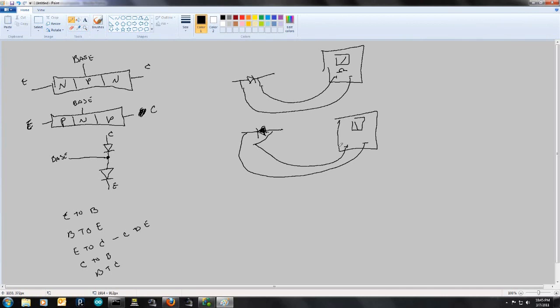So you should measure a very high resistance in one direction and a low to moderate resistance in the other direction, depending on how you're measuring. But basically, how I do it, and I won't go through all this: first of all, PNPs and NPNs are relatively inexpensive. It's a lot harder to measure these components when they're actually in a circuit, so you run into some problems. But if you're testing anything, I highly recommend, you'll see it below.